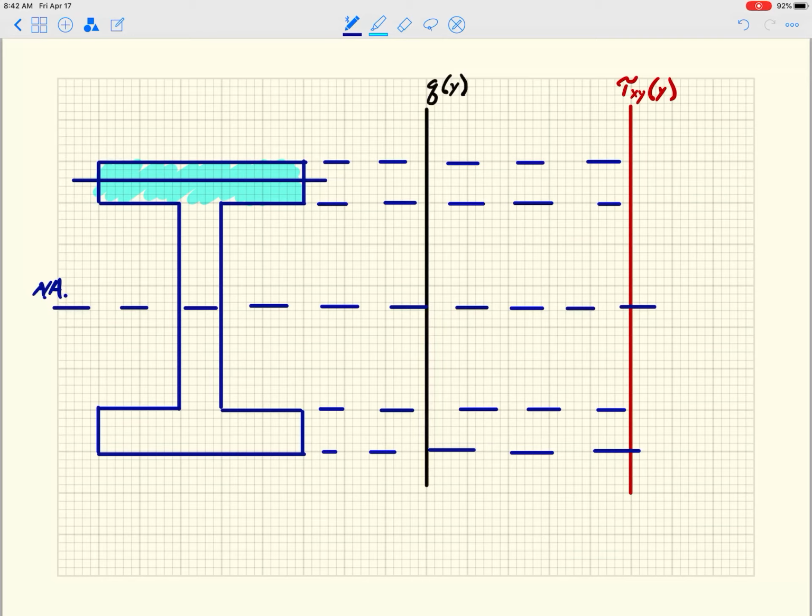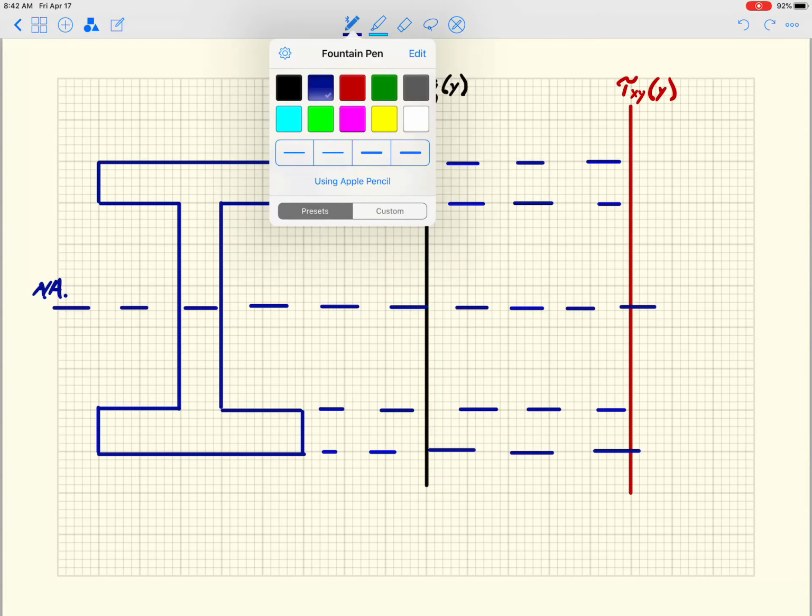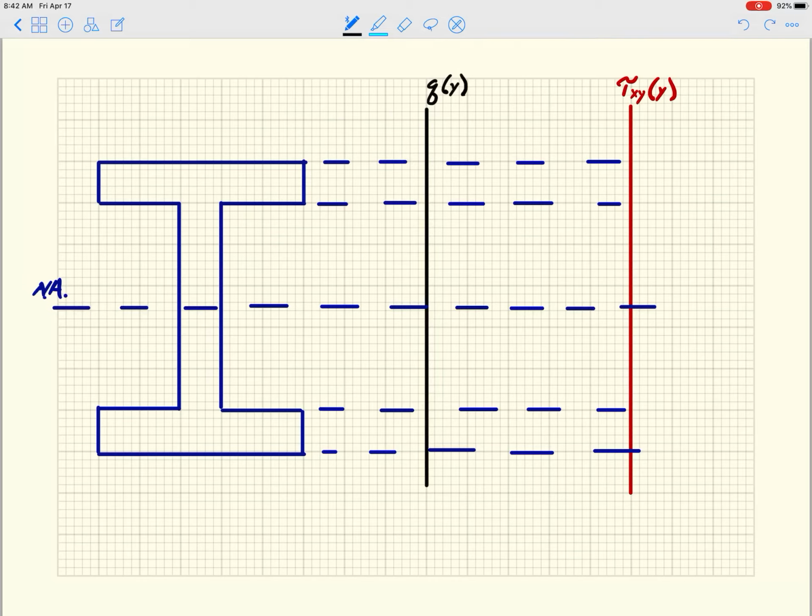So as this line that I've drawn there starts to drop, the area above it is growing pretty rapidly, right? Again, everything is relative, but for example, if it's a half inch down from the top of the top flange and I move it another half inch down, I have doubled the area, right? So in that location, Q is actually increasing relatively rapidly, and what that looks like, if I'm going to plot that here, is something like this, right?